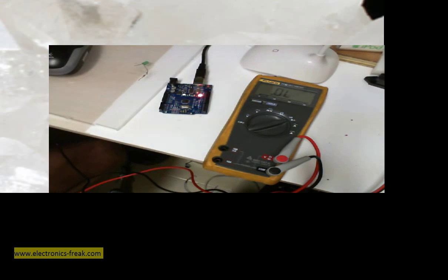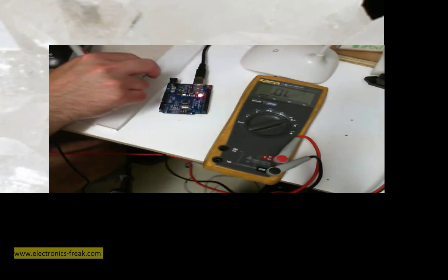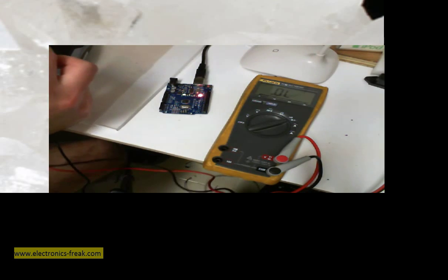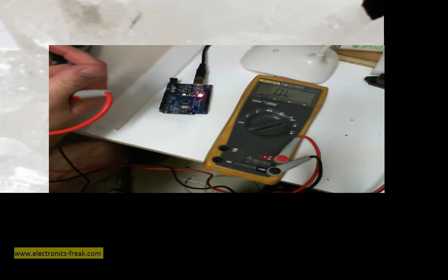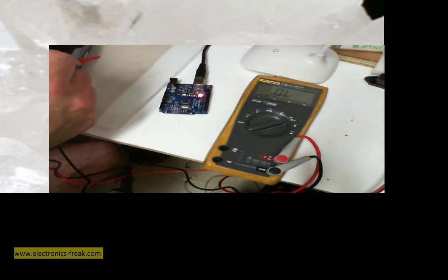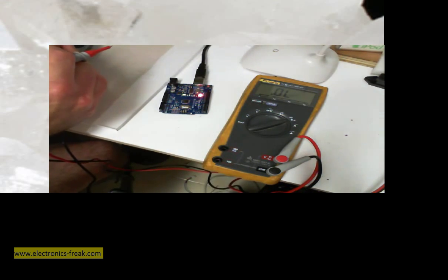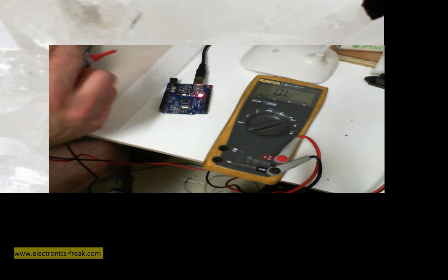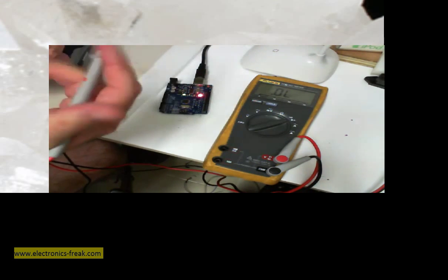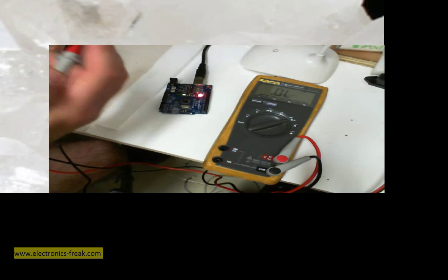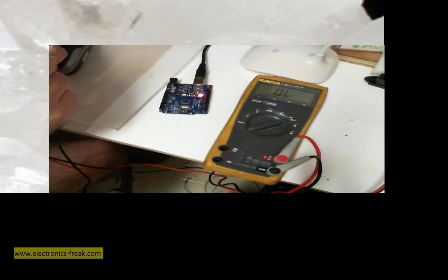If you are not sure about the positive and the negative, first of all, the negative is cut. The edge of the LED is cut. We can use a multimeter to measure it. Not every multimeter, because the cheap multimeter usually does not output enough voltage in order to see which pin is what. In this example, this is a fluke, this is a good one.